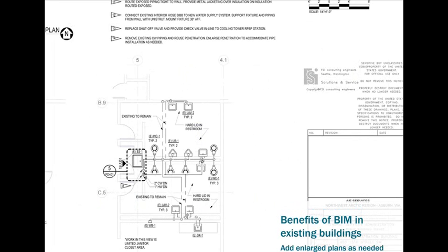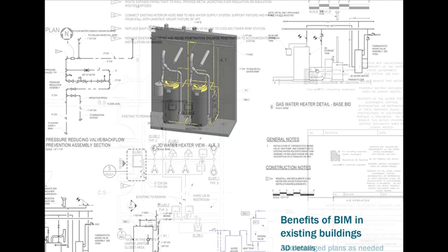Because we had everything modeled, from the point of water coming into the building, the water main, all the way out to every fixture, we could just go ahead and make enlarged plans, whatever scale we needed in order to pump out a clear set. In this case, this is a 3/8 inch equals 1 foot scale set, and it's a little odd scale, but when we tried quarter scale, it didn't look good, so we changed the button and, bam, it changed everything. So that one step of moving everything from quarter scale to 3/8 scale could have taken a lot of time, but since we're using this, it didn't. Saved us time, sped up production, increased clarity.